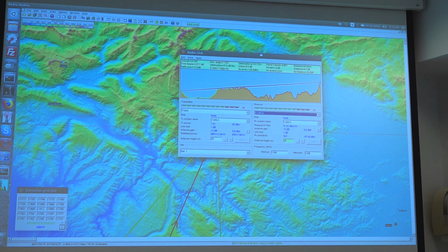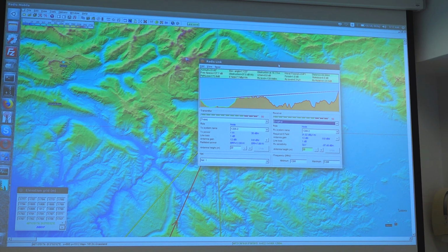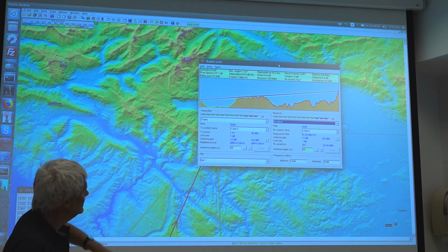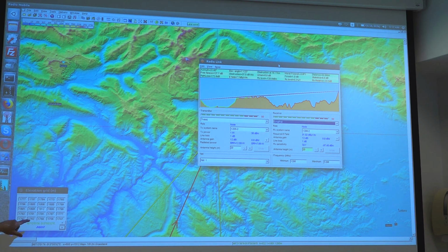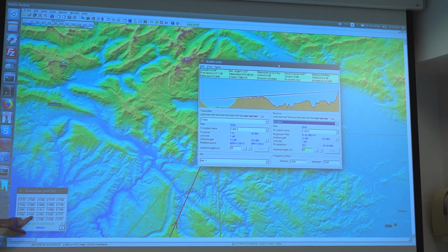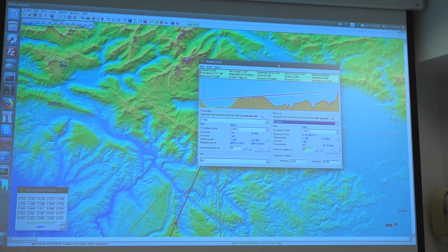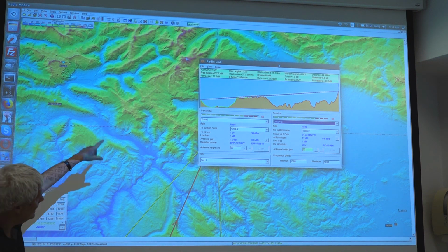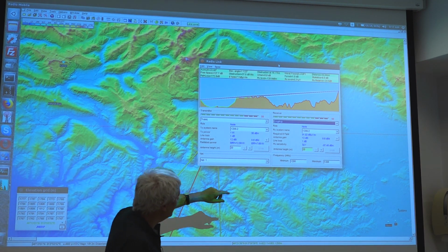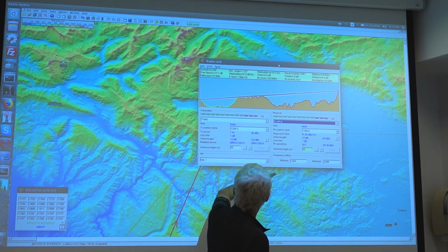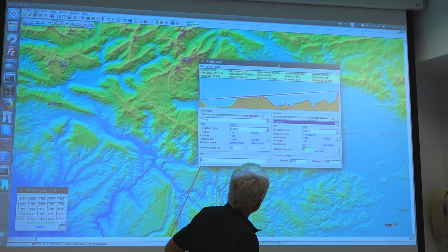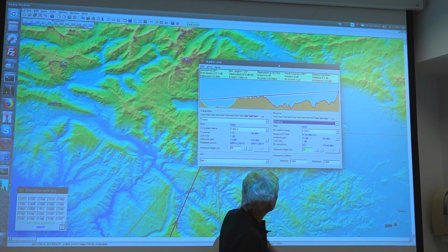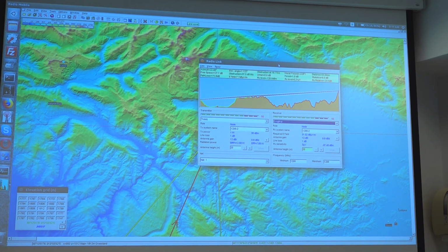Yes, this link has a problem because it has Tarnowski Ghost in between, the peaks of Tarnowski Ghost. But his map is not particularly accurate. You see that this altitude of Černá-Prst, it's actually the tallest peak, but the map is not particularly accurate. What can I do in this case? I can put here the real altitude in the unit properties, or I could raise up my antenna. I can increase here the antenna height to see what happens. I will increase the antenna height, so I go down here, and I increase the antenna height here.